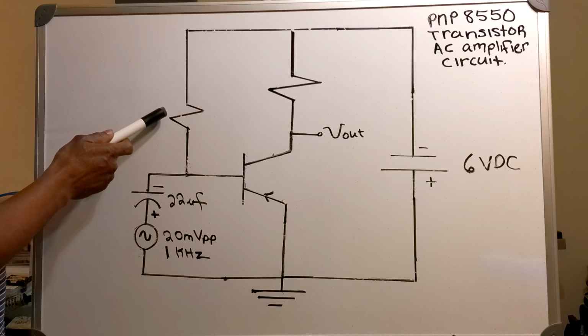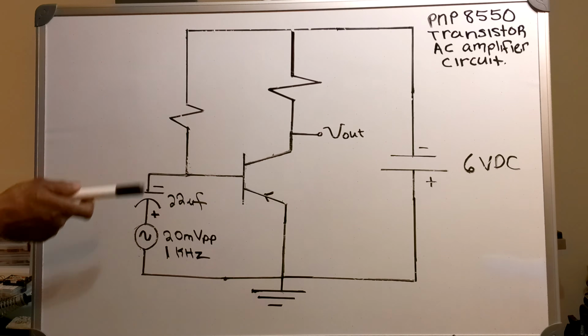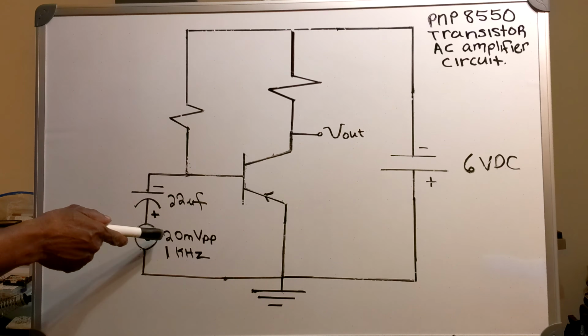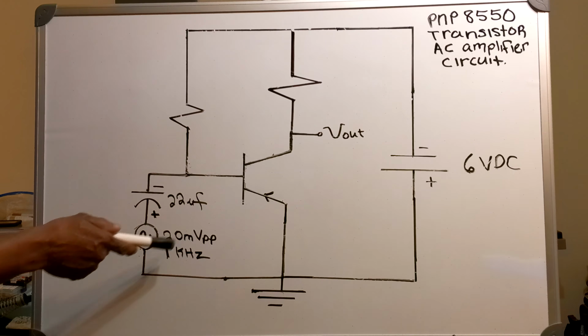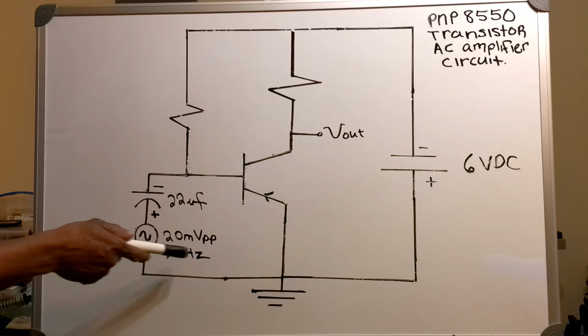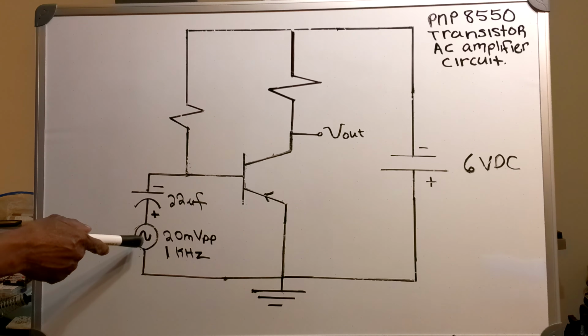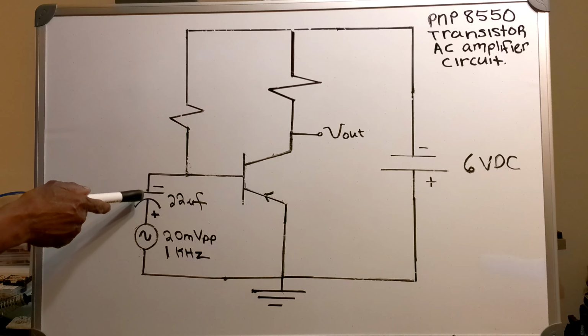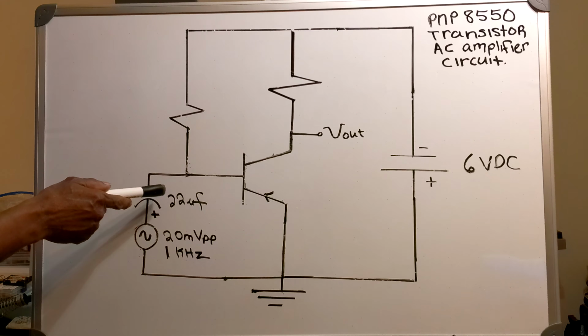On the base, a resistor, and coming off the base, I've got a 20 millivolt peak-to-peak 1 kilohertz sinusoidal input in series with a 22 microfarad capacitor.